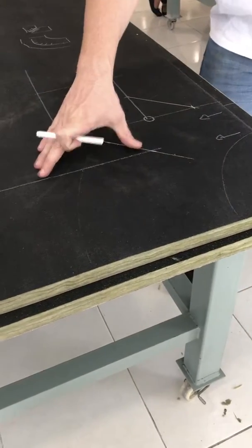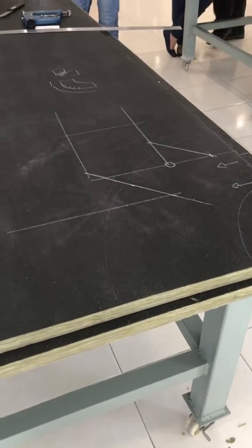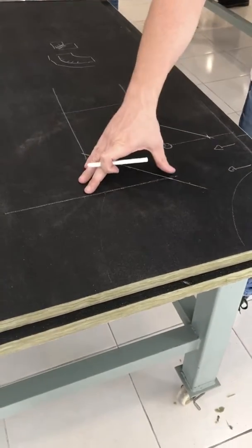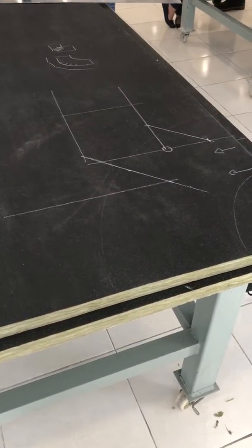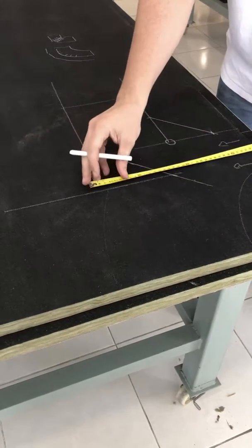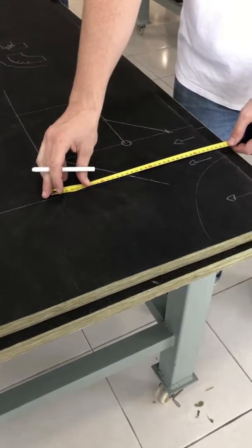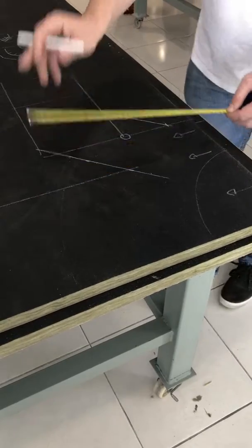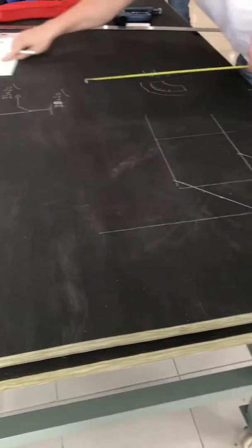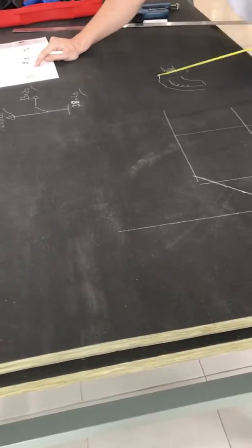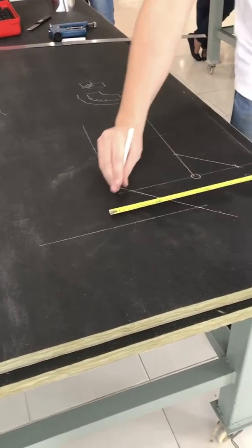And the final one, I would say to you that this piece, due to how we are gonna do the walls, I prefer that you give it here more than 15 centimeters, okay? Indeed, in the brochure you have from 15 to 20 centimeters more or less.